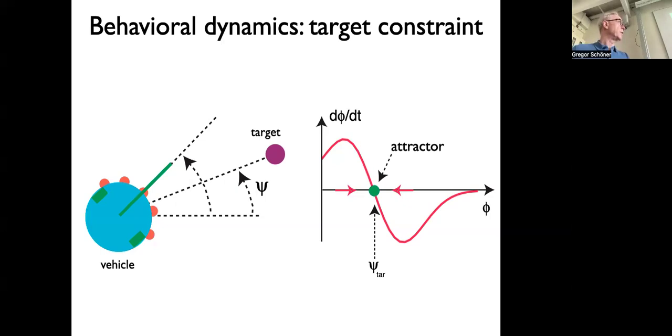Now there is one complication: we have an angular variable, not a linear variable. Therefore, when you're turning 360 degrees, you're back to the original variable. So what we want is a function that's periodic, a sine or cosine function. Actually, for heading, we really want it to be periodic, because even if the target is exactly in the back, we want to still be able to reach it. And so we still want to turn if it's in the back.